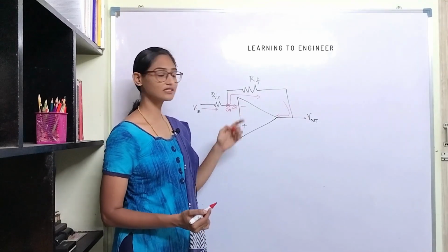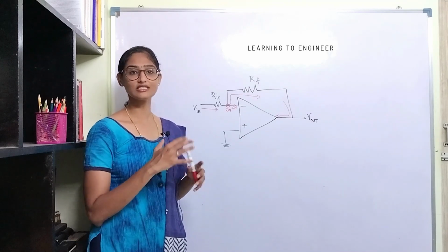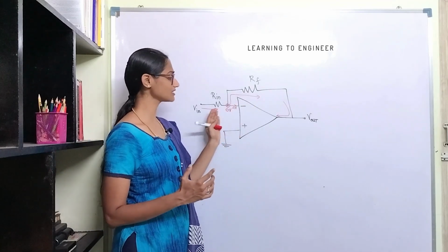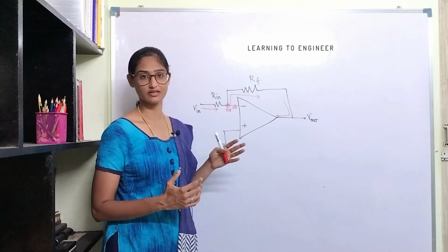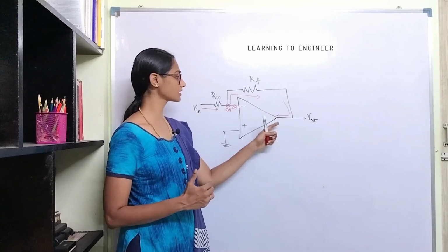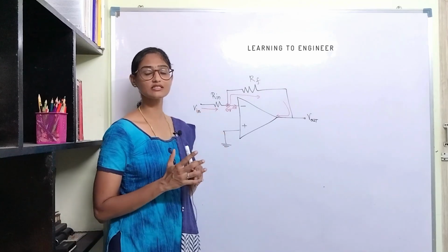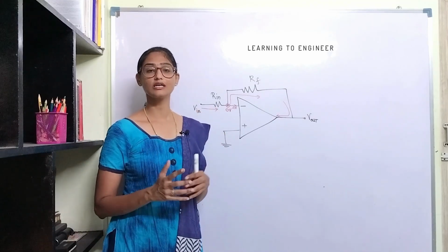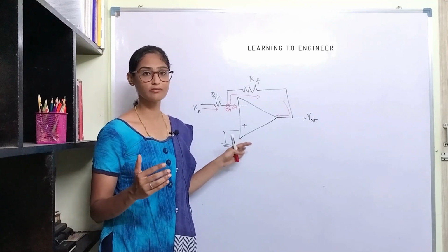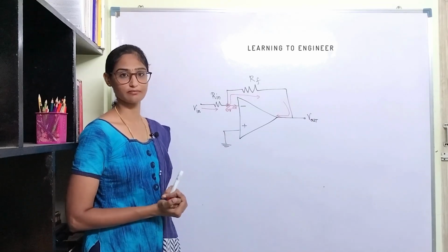If you have supplied that to a negative terminal, in a negative feedback case, this is a degenerative feedback, meaning the error term will be subtracted from that input current. So constantly this will be generating the output signal in a degenerative manner. Whereas when you have positive feedback, the signal goes on increasing and it will drive this op-amp into saturation. I'll explain this with an example.